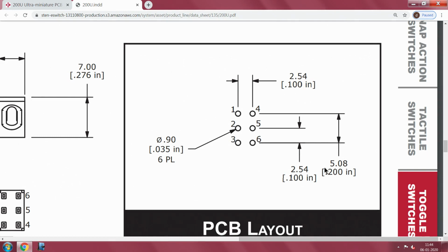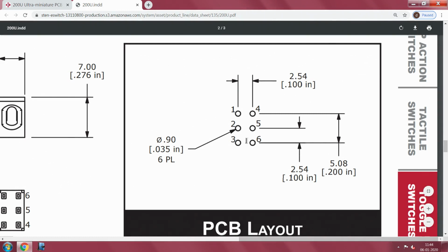So, especially if you are going to have a large number of components and all of them are going to be mounted on a printed wiring board, and the printed wiring board is likely to be laid out automatically, it is much better to look for devices which will give you this 0.1 inch which is given here. That is the reason why I keep showing you this. You have seen this is a beautiful 2.54, and similarly this is 0.2 inches.